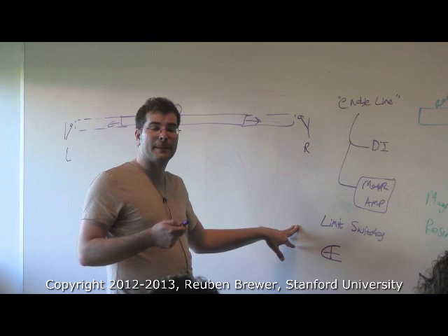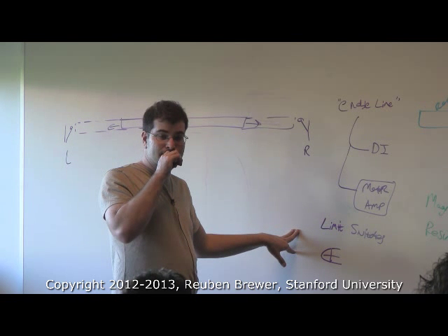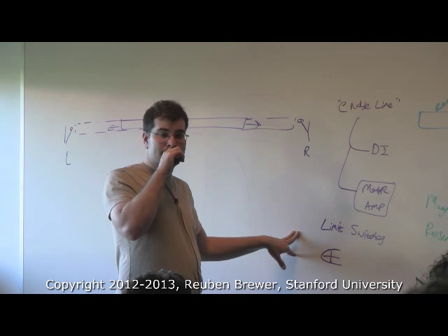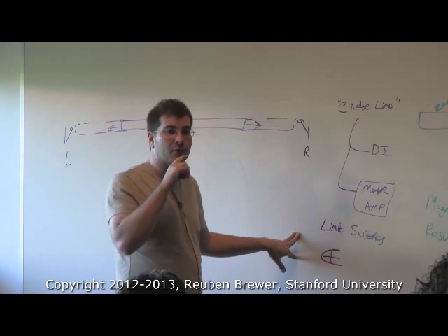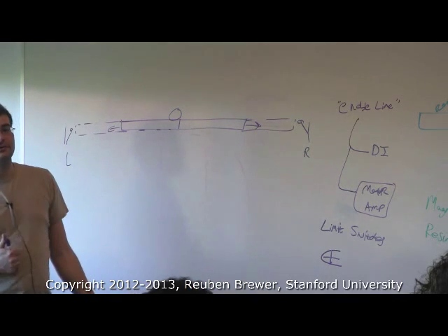Can I do one follow-up? Yeah. For your robot in particular, do you have any spring-loaded stuff so that if you cut power to the robot, the last thing you want it to do is, under the weight of the arm, shove the needle further into the patient? Exactly. The answer is yes. And that is about counterbalancing and backdrivability.